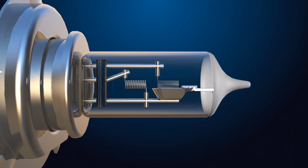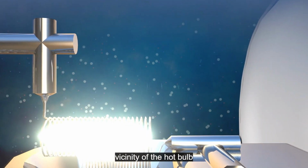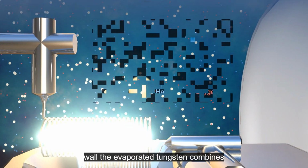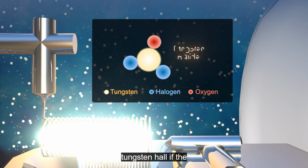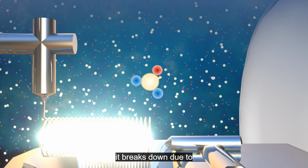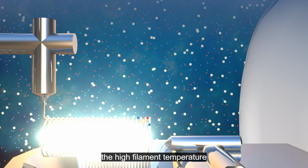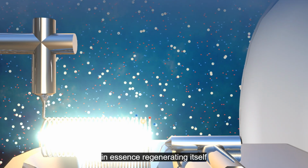When a halogen type bulb is in operation, there is a unique cycle that occurs that increases its service life. In the direct vicinity of the hot bulb wall, the evaporated tungsten combines with the filling gas to form a translucent gas, tungsten halide. If the gas approaches the filament again, it breaks down due to the high filament temperature and forms a tungsten layer, in essence, regenerating itself.